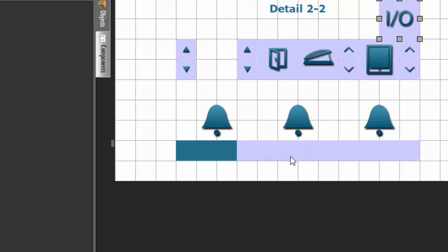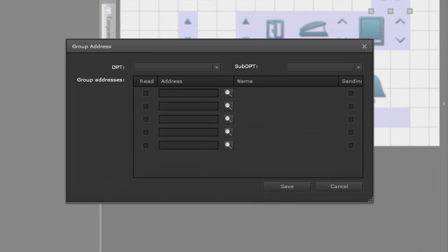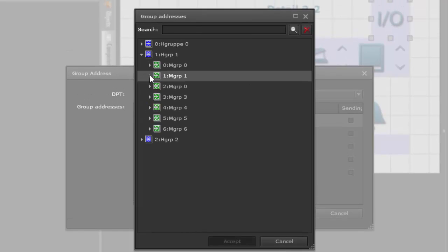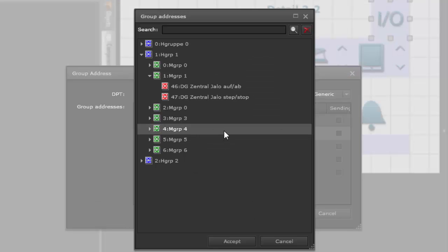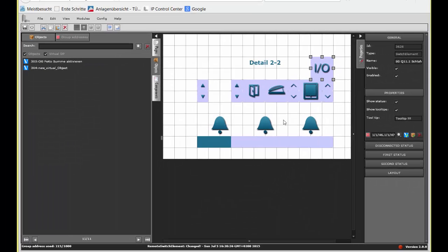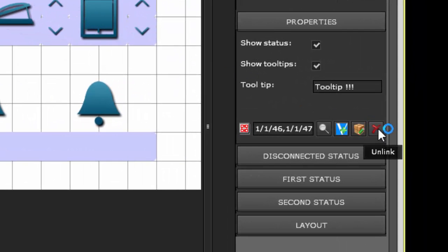This is the same like for the real KNX group addresses. The parcel icon edits the process point, and if one or more group addresses are used for it, you must also define the sending and the read on init group address. A send flag must always be set, like in ETS, even if it is only a status. The red cross deletes the entry.